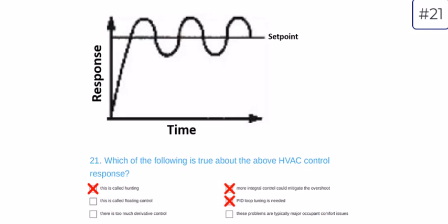You might call this floating control. This actually does look similar to what you'd see in a residential environment. You might have a heating set point and a cooling set point, and you might get past your cooling set point, start cooling until you get to the heating set point, and then start heating. But the profile of this, I would say, isn't necessarily exclusive to floating control, and we're usually looking for this where we have PI loops and are identifying a loop tuning issue.